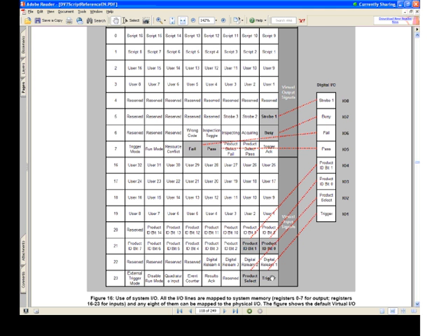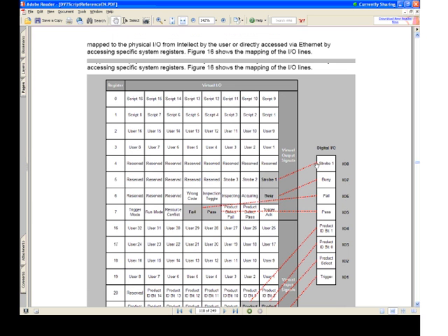And down here in the trigger usually is your input 1, which is register 23. Bit 0, product select, which you and I just used a minute ago, is in register 23, bit 0, or I'm sorry, bit 1. And up here on bit 21 were those product ID bits that we just took a look at. So realize these are all mapped here also.